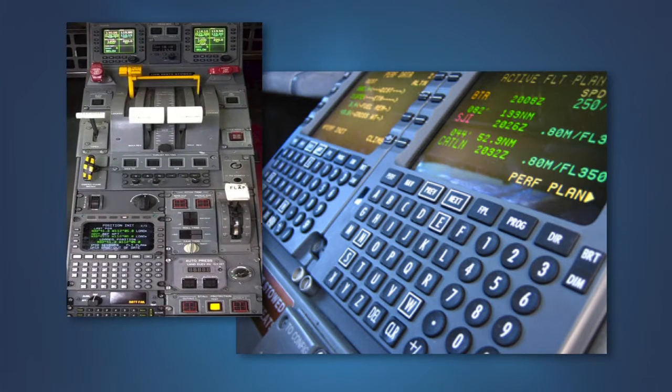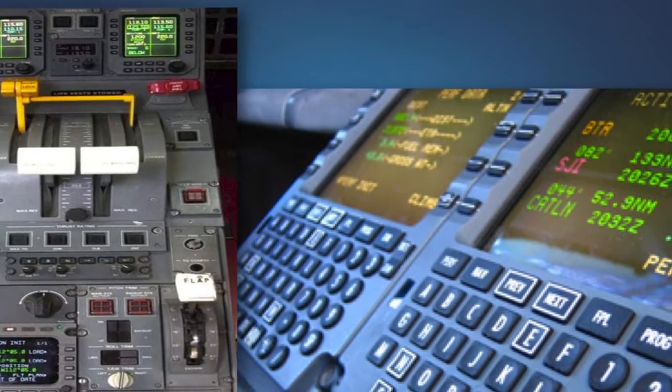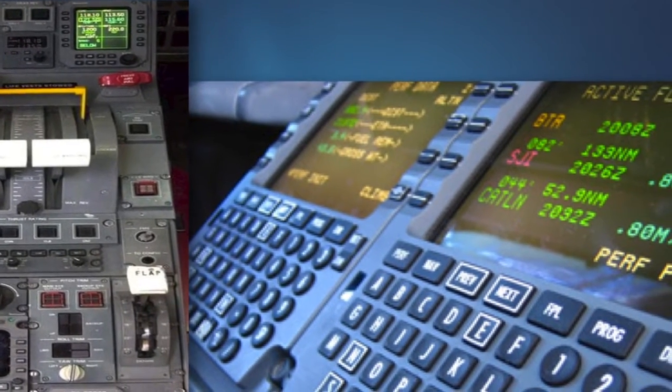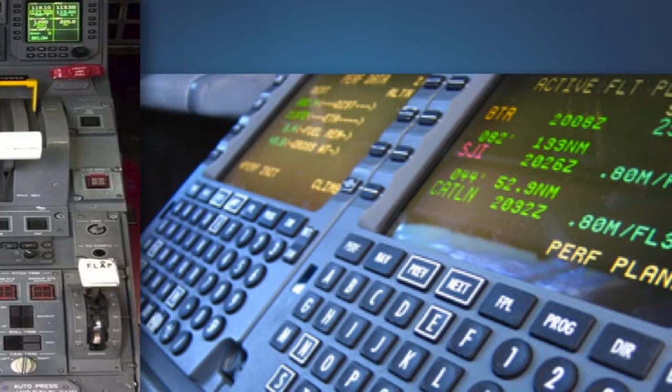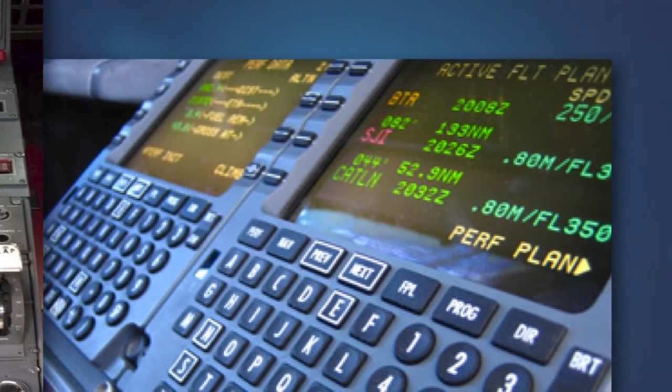The flight management systems on many business airplanes provide features for computing airplane performance, including climb weight limitations. Pilots should be aware that the results provided by these systems are only as accurate as the obstacle information entered by the pilot. If the pilot enters the climb gradient requirement published on an IFR departure procedure, the results may be misleading.